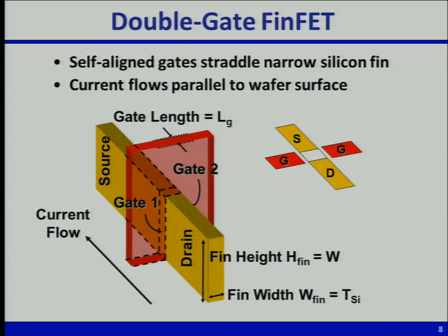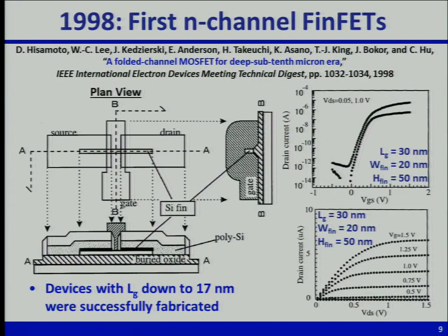Right. So Intel actually put this into production, but let me say a few words about the work we've done to introduce it. So in 1998, that was the first FinFET published by Hisamoto, who was here. The key thing to note is that now you can read these papers, right? You have the current on a log scale versus gate voltage, and that was for a gate length of 30 nanometers. So we didn't quite reach our goal of 25 nanometers in 1998. But see, the width of the silicon fin is 2/3 of a gate length.